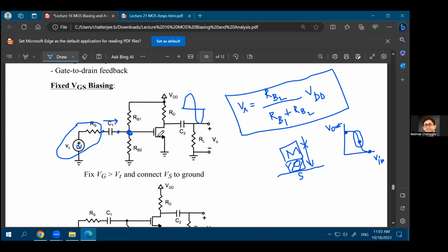have a DC bias point for the MOSFET in the region where your slope of the VTC can be maximized, and at that point you want to apply an AC signal. So that's why you are coupling it with a capacitance. A capacitance lets the AC signal flow, but it will block the DC.